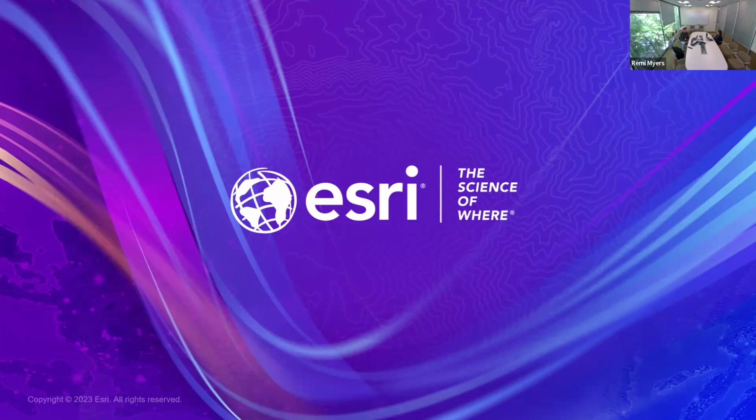I will tell you very candidly that Jack himself insisted that a builder be provided, and it is coming available to the public in the next network management release of ArcGIS Pro 3.5 and ArcGIS Enterprise 11.5, a migration builder or migration wizard. What this wizard will do is take a geometric network or any other sort of unstructured data and create a very simple utility network that does not necessarily have rules.